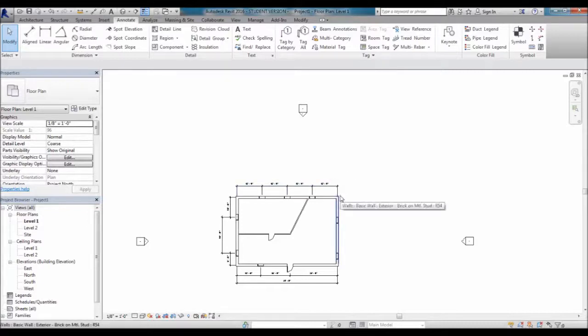So instead of saying, from this corner of the building here to an object that's out here on the top right, instead of giving you a dimension that goes on a diagonal from this point to that tree and says that, on a 75-degree angle, go 10 feet, it might say, okay, from this point, vertically up from here is 15 feet, and then take a right turn 90 degrees and go another 10 feet, right? And that kind of gives you an idea of how you can locate that object without having any sort of landmarks around you.